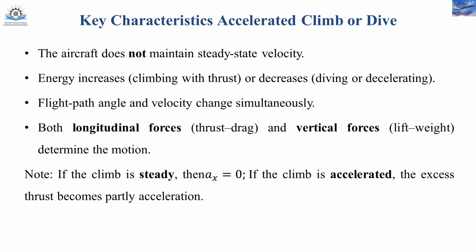Both of them change simultaneously. Both longitudinal forces and vertical forces determine the motion. So if the climb is steady, then acceleration in the x direction is 0. And if the climb is accelerated, then the excess thrust becomes partly involved in the acceleration. So that is the meaning.